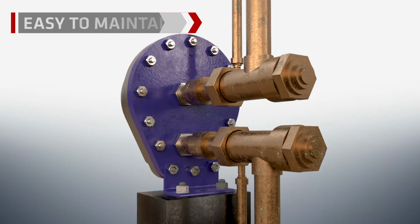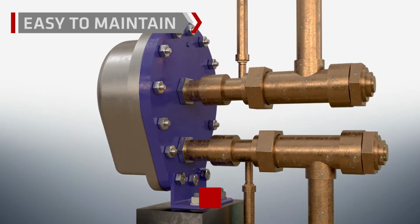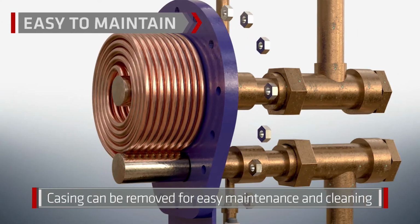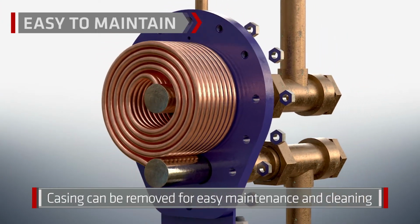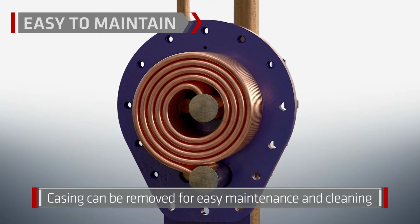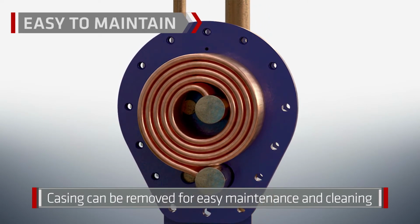One key feature of Heliflow heat exchangers is that you can gain access to the shell side without disrupting the piping. You just unbolt the casing from the base plate, remove the back side of the casing, and then you have access to power wash or clean the shell side.